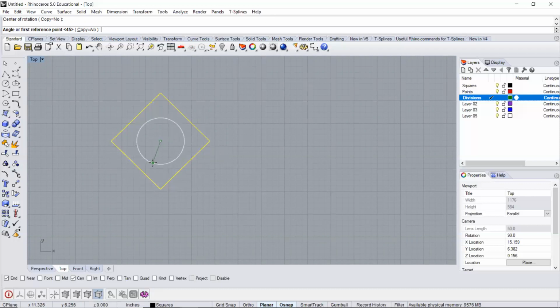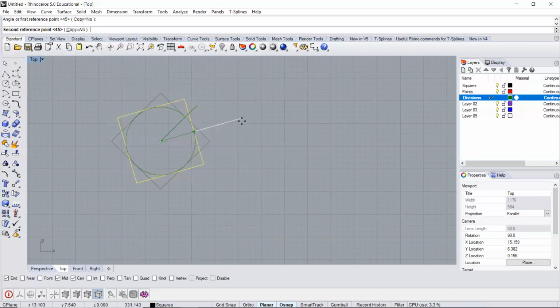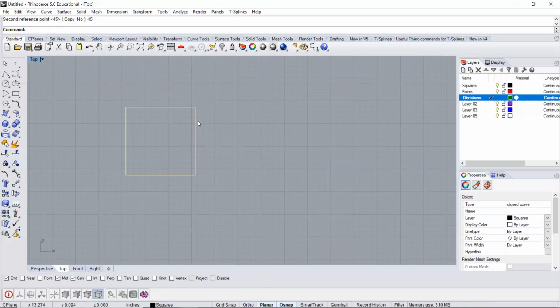And I'm going to turn on my midpoint snap now. What I'll do with my midpoints on is that will let me go to the center of any of my lines. And so once I'm at my midpoint here, I'll go ahead and click. And now I'm rotating my square from its center point. And if I wanted to get this back perfectly horizontal and flat again, I might want to turn on my ortho. And that way I can snap it down right back to where it was. Or I could uncheck ortho and I could type in 45 once again and say enter, and it'll rotate right back to where it started.